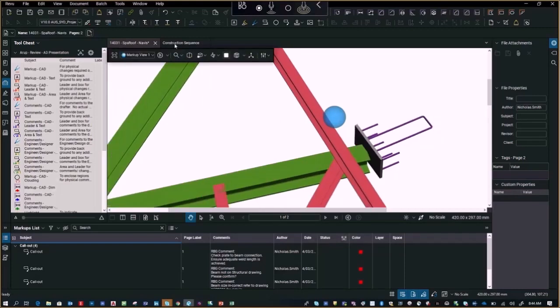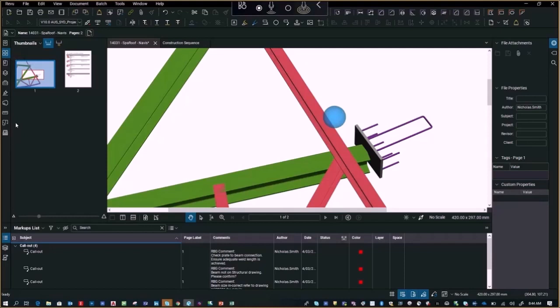If you have too many markups on different layers, I think it spits it out as different markups in different boxes, rather than just one markup. So if you put the markup on and draw a few detail lines, that will be a separate markup rather than combined. You need to group it. If you're using spaces out of Revit or something like that, as long as you don't exit that markup view, it should all be the same one.